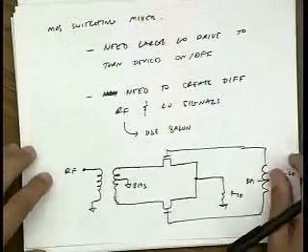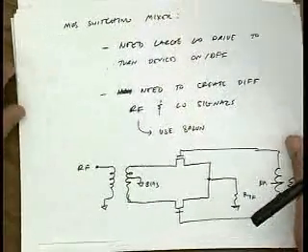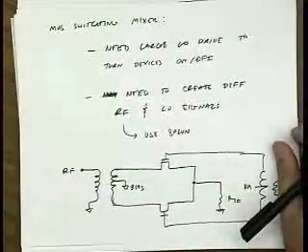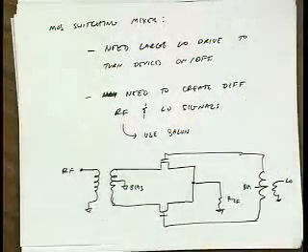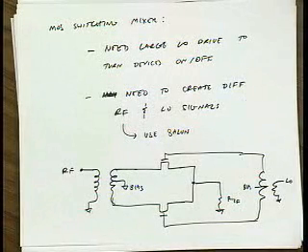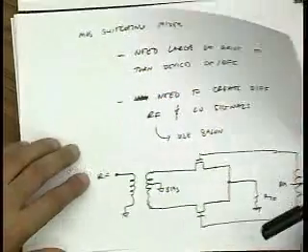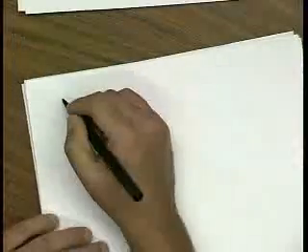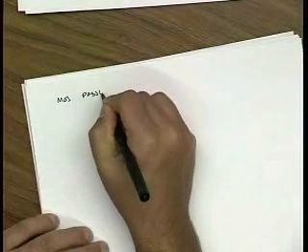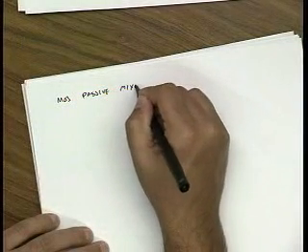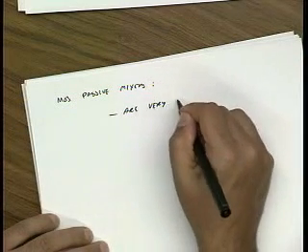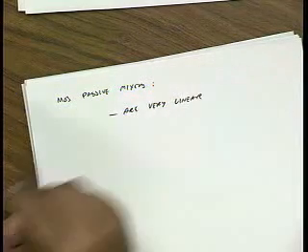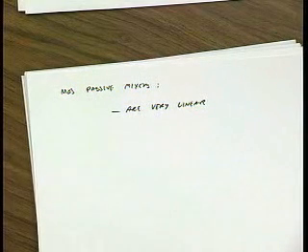Okay, well, in fact, a more popular version of this mixer is... actually, before I do that, let me say a couple things about noise and distortion. Distortion: these devices, so passive mixers, MOS passive mixers, are very linear. Okay, why can you make that claim?